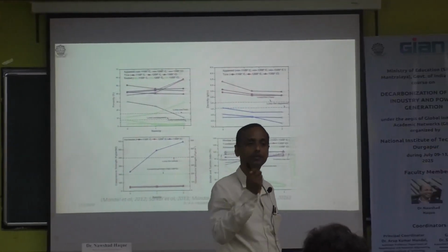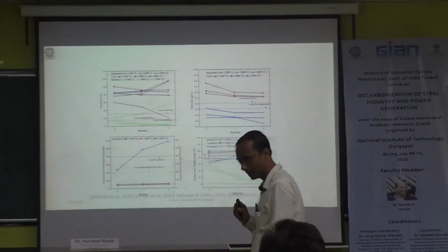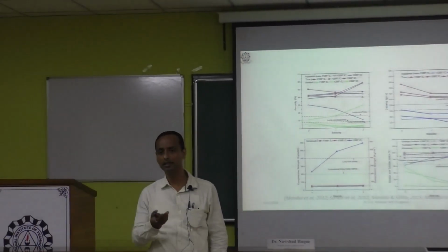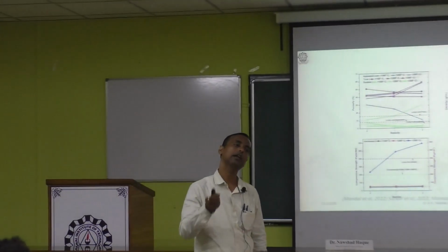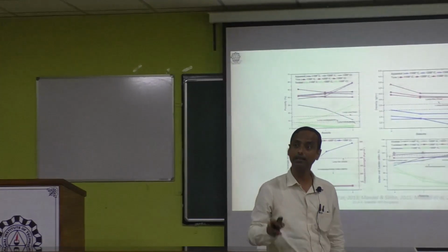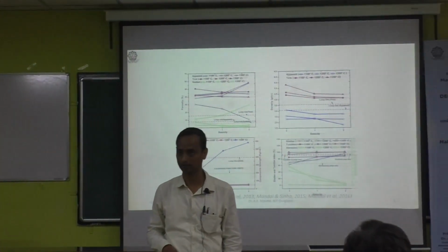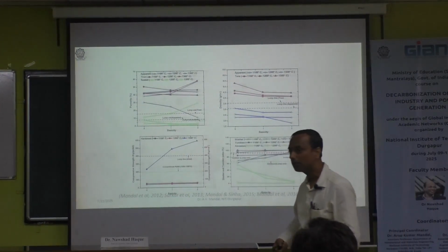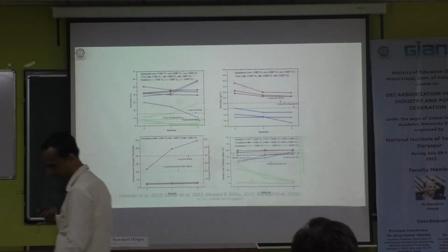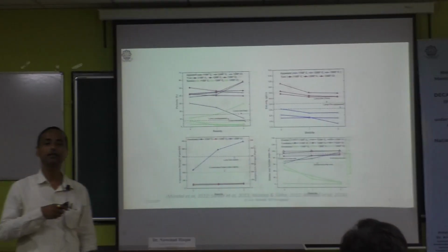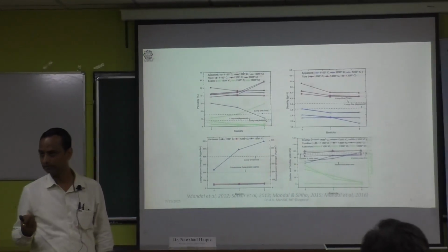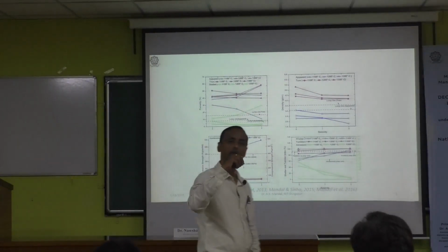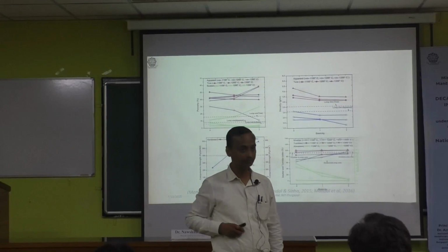Therefore, in the green condition, if you want to make the pellet, you have to prepare slaked lime. Means calcium hydroxide formation is required first. After that, one is slaking here. After that, you can add that lime and you can make the pellet. Then this slaked calcium hydroxide will act as the binder also. It will bind. Number one problem can be solved. Number two problem will be when you go for the higher lime content. These pellets will be utilized in the blast furnace, because we are discussing the flux pellet, not super flux pellet. Then after making the pellets, what will happen? It requires drying.